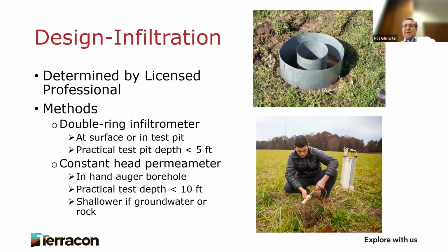Okay, infiltration rate. Determining the infiltration rate of the in situ soil is also an important step in the hydrogeologic design process for stormwater control measures. For infiltration devices and permeable pavement, infiltration of water down through the in situ soils is necessary for treatment and volume control. The infiltration rate is needed to design those stormwater control measures. It's also advantageous and sometimes necessary to have low permeability in situ soil for systems with permanent ponded water like wetlands and wet ponds.